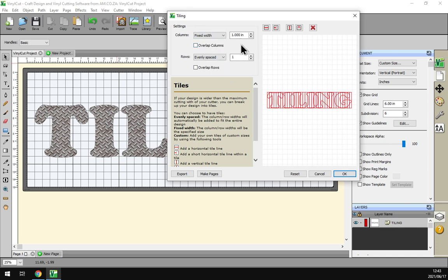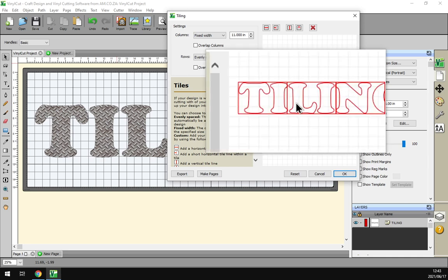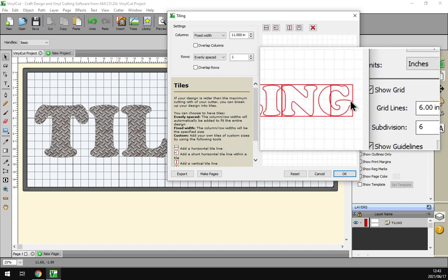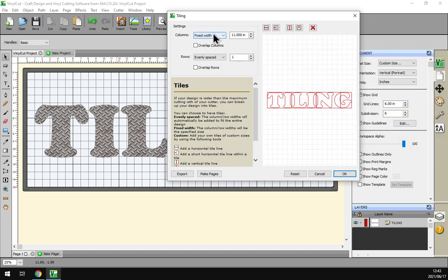Let's say your vinyl cutter can maybe cut a max of 11.5, or rather say 12 inches. So then you'll set this to something like 11 or 11.5 inches. And once we click out of it or press enter, you'll see it breaks it into cuts where each cut will be 11 inches and the remaining will be the rest. That's quite nice if you go fixed width, if you know exactly the dimensions your cutter can handle. And then last up we've got custom.